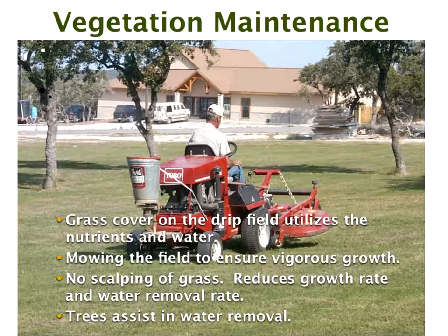I'm going to ask a question here. This has got nothing to do with this particular topic, but it's relevant to our industry. People frequently, not when you're putting in a drip drain field, as I stressed earlier on, keep the trees, go through the trees, perfect. But most drain fields, you cannot allow trees anywhere near them. Particularly conventional drain fields, and drip is probably something like 1.5% of the market. So we've got the other 98.5% of the drain fields that go in.